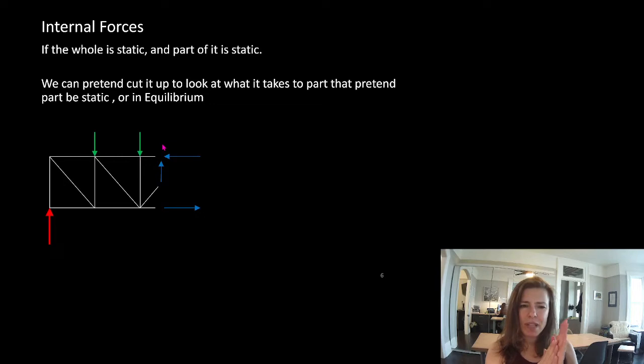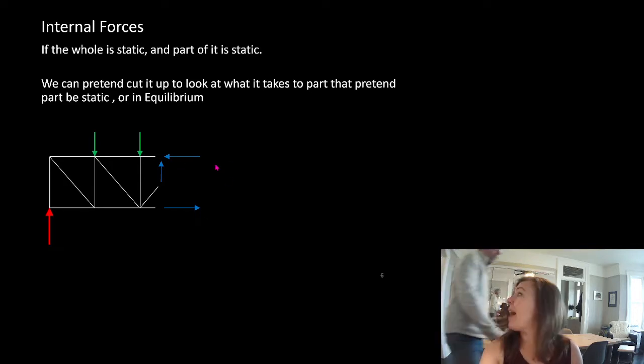That looks a lot like our shear force. And look at this, a top element in compression and a bottom element in tension. These look equal and opposite, some distance apart from each other. We tend to talk about that as moment. Okay, so maybe we could redraw that as moment.